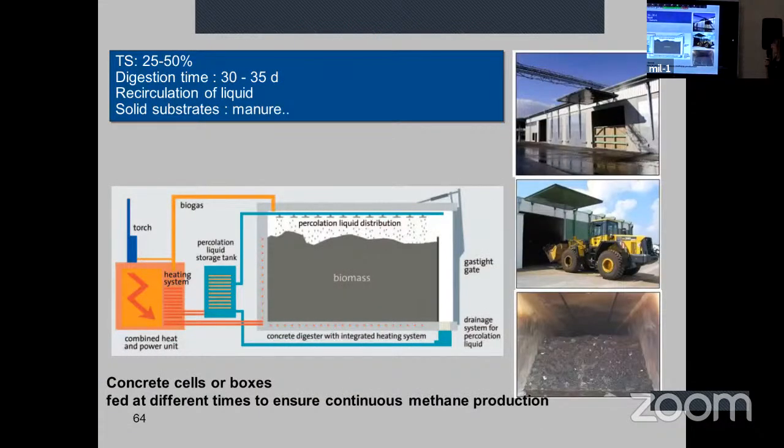And yeah, the batch reactors that are more operated at farm biogas plants. So you can see the garage where, thanks to the tractor, you put your waste. Most of the time it will be manure and also some digestate, and you will throw some liquid through the garage.